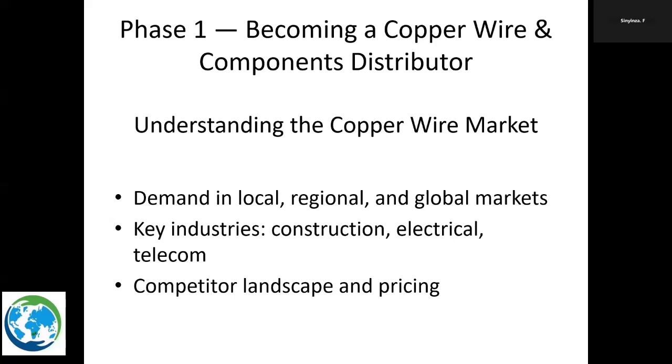like if you need to have earthing, you will have another core inserted, which will normally be green if we go by the British specifications for house wire. And if you look at the plug, for those of you that have 3-pin plugs, you find that the earthing is normally green, or it's green-yellow.